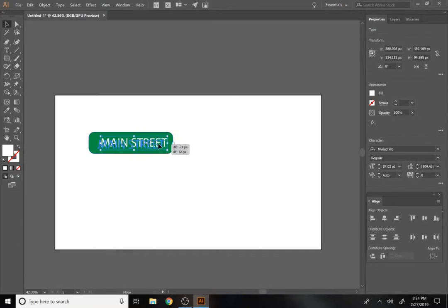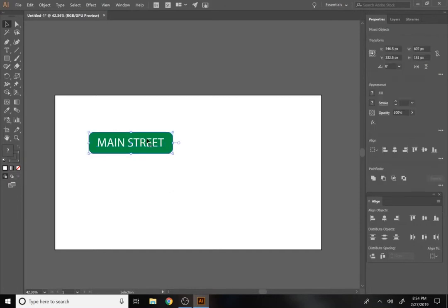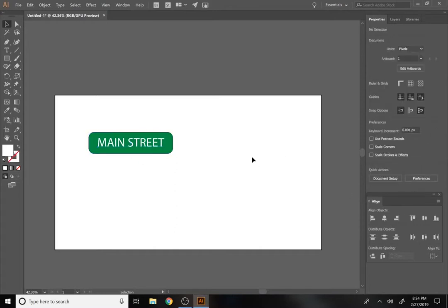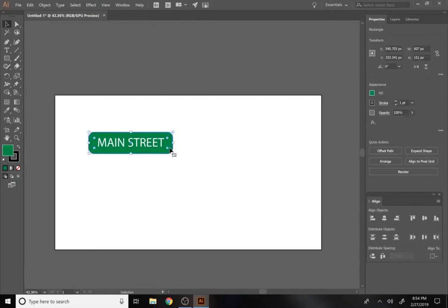And if, for instance, you wanted to create a border on the inside here, just a fun little thing, you can select both of these, and you should see this little align option right here. Usually it'll be set to selection right there. If you don't see that, you can just choose selection, which is basically everything we have selected. We can center them by clicking these little buttons here in the middle just to make sure they're centered.